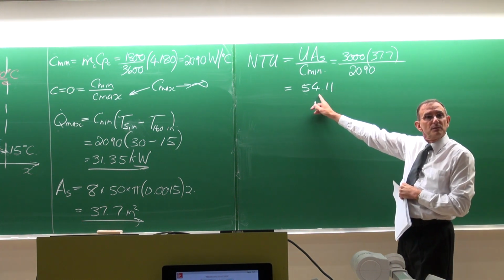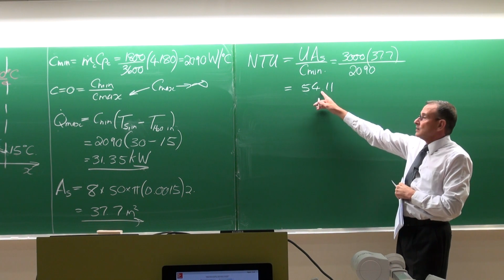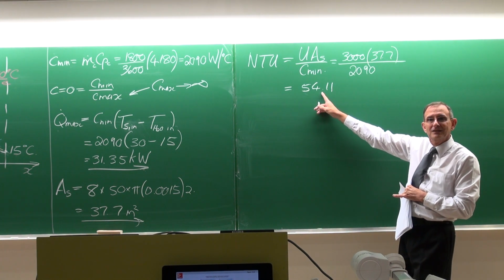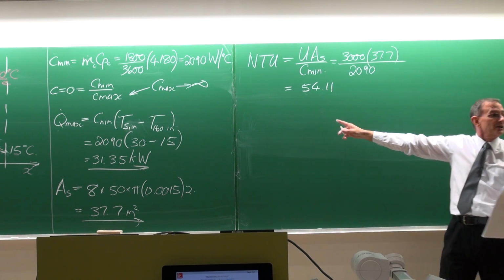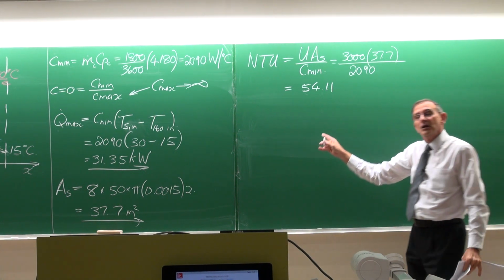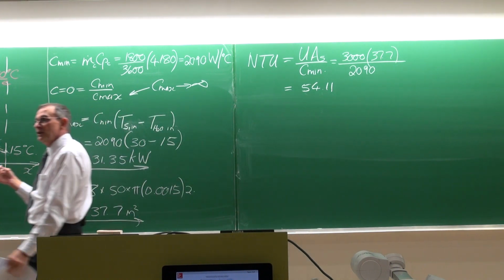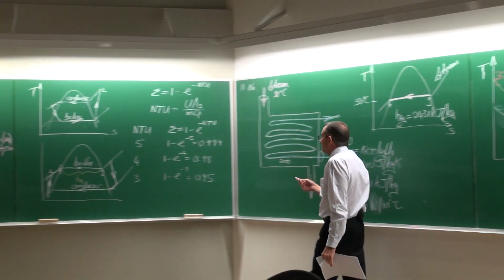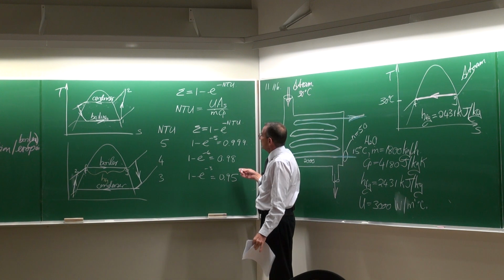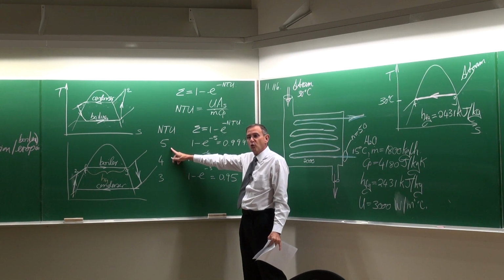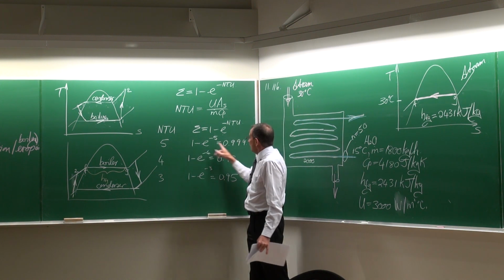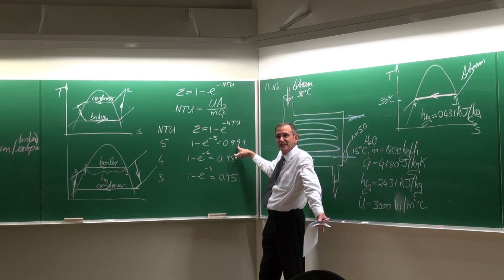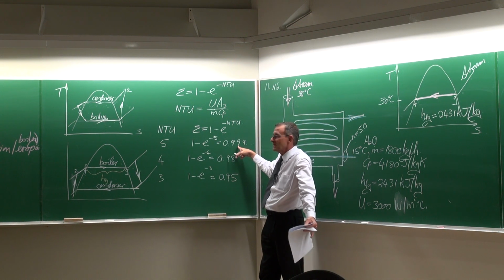Now, if you've done some heat exchanger design, you should frown here, for 2 reasons. Firstly, maybe you've made a calculation error, so you need to go and check this. But coming back to what I've already warned you on in the chapter on internal forced convection, if your NTU is more than 5, you're wasting money, because your effectiveness will already be 100% for all practical purposes.